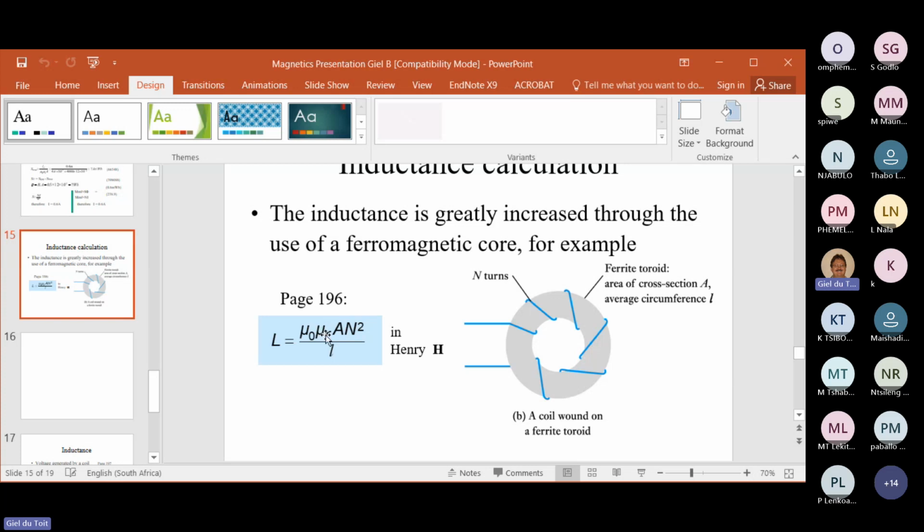The relative permeability. The area is, if I cut this thing through in half here, then that cross-sectional area that is there, that is your area, and it's in square meters. Don't use square millimeter, don't use square centimeters. It will be wrong. Always convert to square meters.